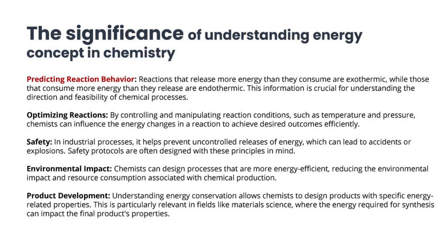Yeah. What else? Second, optimizing reactions. If you know it's exothermic, maybe you need cooling to control the rate. If it's endothermic, you know you need to supply heat. Understanding the energy helps you tweak temperature, pressure, things like that to get the best yield. Makes sense. Controlling the conditions. Third, and this is huge, safety. Right. Uncontrolled energy release. Bad news. Very bad news, especially in industry. You have to know the heat of reaction to design safe equipment, cooling systems, emergency procedures. Think about large-scale polymer production, often highly exothermic. Get the thermodynamics wrong, and you risk dangerous runaway reactions.